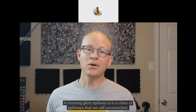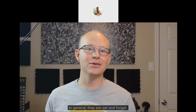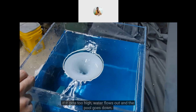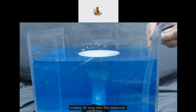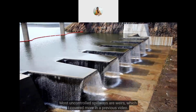A morning glory is in a class of spillways we call uncontrolled. In general, they're set and forget. There are no gates or moving parts to manage. They regulate the reservoir simply by existing. If it gets too high, the water flows out and the pool goes down. If the pool is below the crest, no water is released and the level goes up as precipitation makes its way into the reservoir. Most uncontrolled spillways are weirs, which I covered more in a previous video.